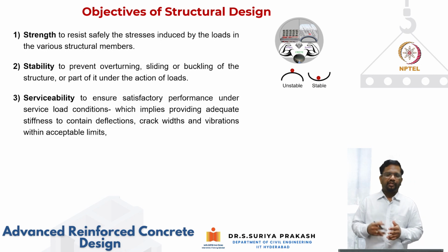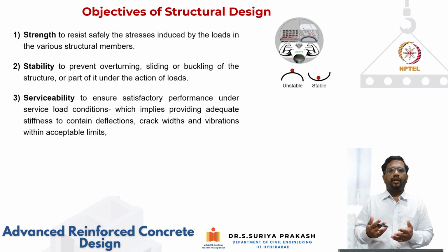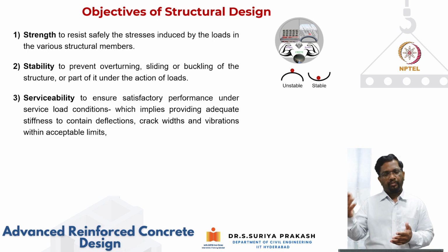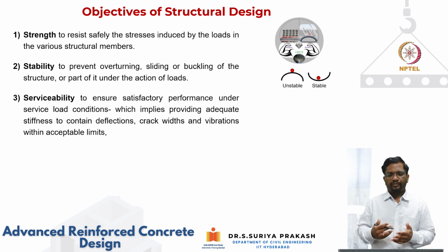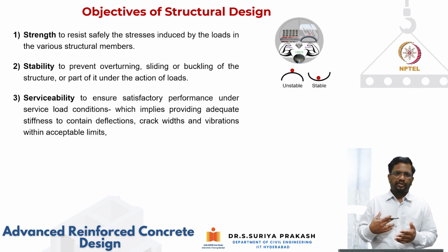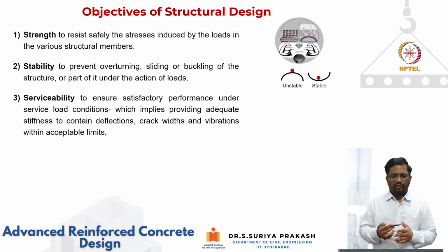And the structure should be serviceable. What is the meaning of serviceability? It should ensure a satisfactory performance under service load conditions. The strength may be adequate, but if the structure is not serviceable, it is not going to serve the purpose. So it should contain adequate stiffness to make sure that the deflections are not very high, and the structure should not have larger crack widths. Most of the time we want a crack-free structure in a reinforced concrete element, and vibrations also should be within acceptable limits.